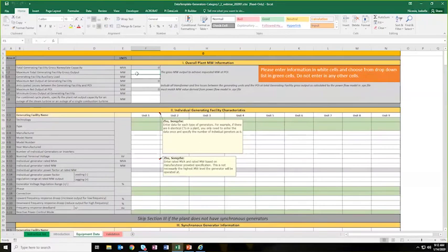Depending on the technology, like solar plants, those inverter-based power plants typically oversize the inverters. So do pay attention to this one. Don't enter the total rated megawatt. This is the total output you should produce to achieve the megawatt at POI. So here there is some math we should match up.